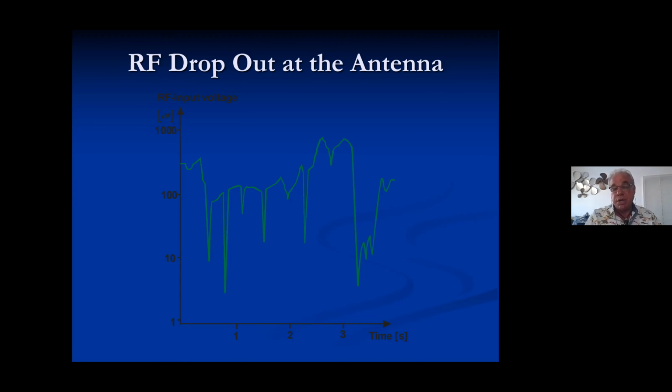So what you're looking at here, in my opinion, would have happened because of a polarization dropout. Polarization dropouts are when the RF hits a wall or a metallic surface and flips in polarization. So here's another scenario: someone has a handheld mic and it's a dipole, and they pick up the mic to sing sideways, and suddenly now that RF is traveling through space on a horizontal plane, and your antenna is on a vertical polarization. Those dropouts look to me like they would be either polarization dropouts, maybe multipath cancellations. Getting ahead of myself, that's June 22nd. We'll talk about that a little bit.